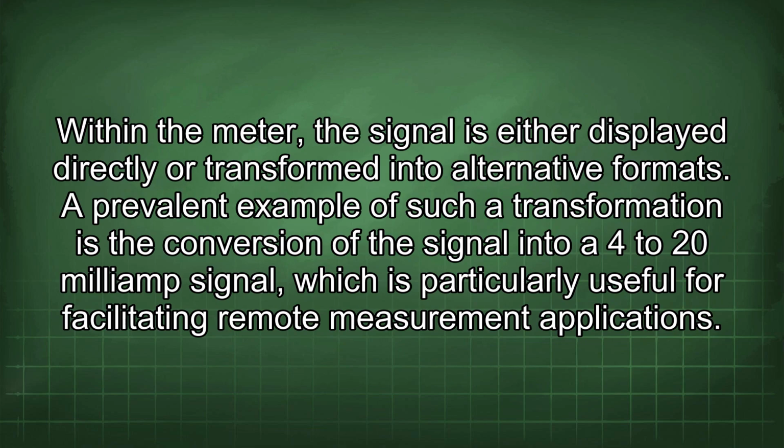Within the meter, the signal is either displayed directly or transformed into alternative formats. A prevalent example of such a transformation is the conversion of the signal into a 4 to 20 mA signal, which is particularly useful for facilitating remote measurement applications.